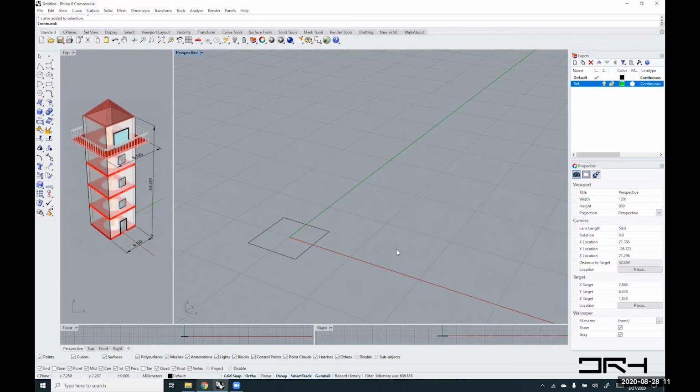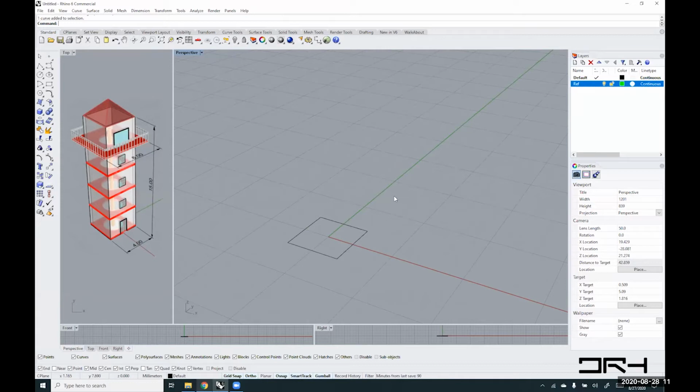One of the things you need to remember is that our dimensions are in meters here, and I didn't check if my Rhino environment is actually using meters. One of the places you go to is here down the bottom, and you'll see that it reads millimeters. So what I've just created is 4 by 4 millimeter for the base of my Lighthouse. So how can I change that?